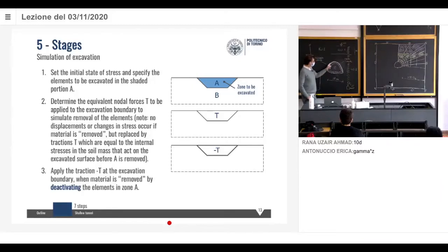Because when we excavate the first cross section, you remember from rock mechanics that in order to simulate an excavation, we decrease the internal pressure, isn't it? And we can do that gradually. If we do it gradually, it's better than doing it at once. So that means we may run separate construction stages to simulate the excavation.